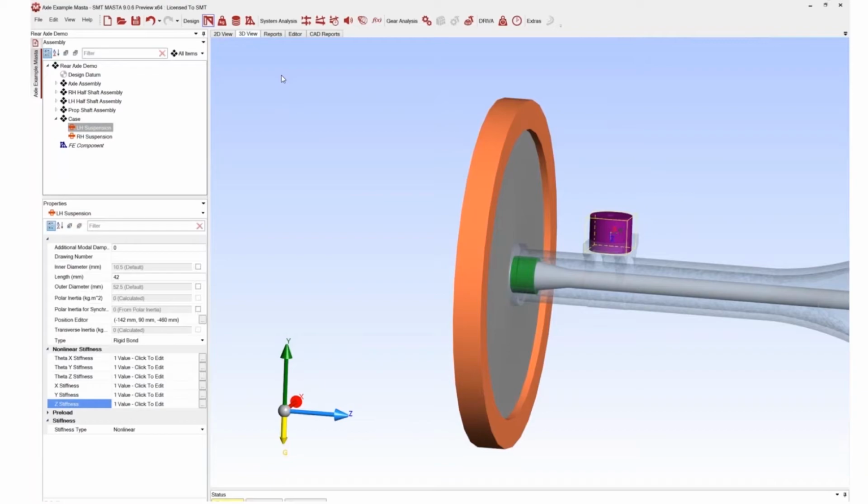First of all, someone's asked about frequency dependent damping on a coupling. That's not something we offer at the moment. We have an additional modal damping factor that can get added, but that's not frequency dependent. It is just what it is. So that gives you some extra damping on that component proportional to the strain energy of that particular mode.